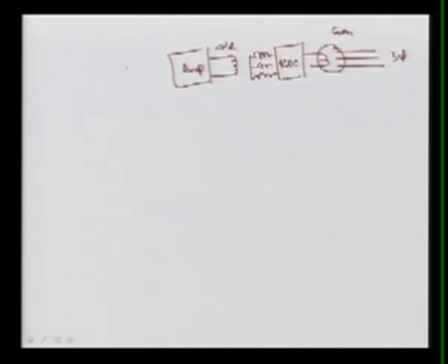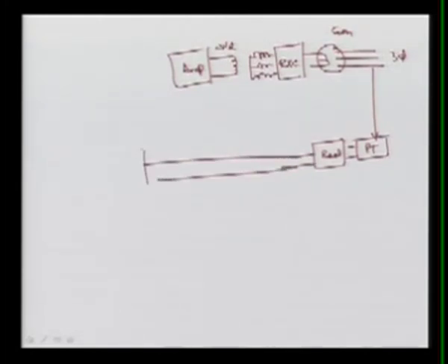Now here we have another, basically we had the comparator, meaning we measured, again you remember, using the PT, the potential transformer, meaning we are measuring voltage, and this is now given to your rectifier circuit, meaning we are getting some DC voltage, and this DC voltage is again compared in the comparator, and then we get the V reference value, and this gives your change in E, that is the error.